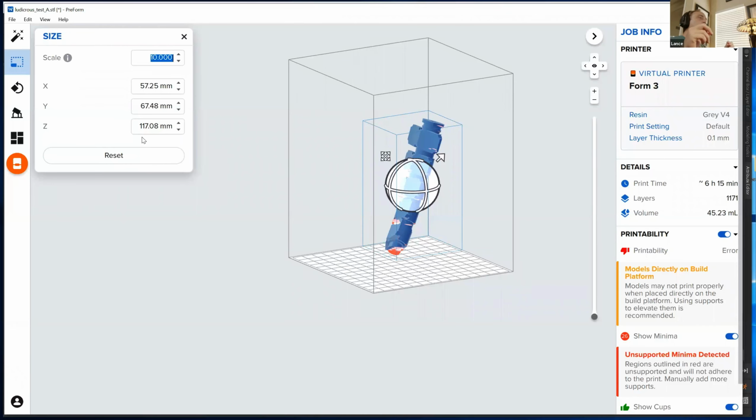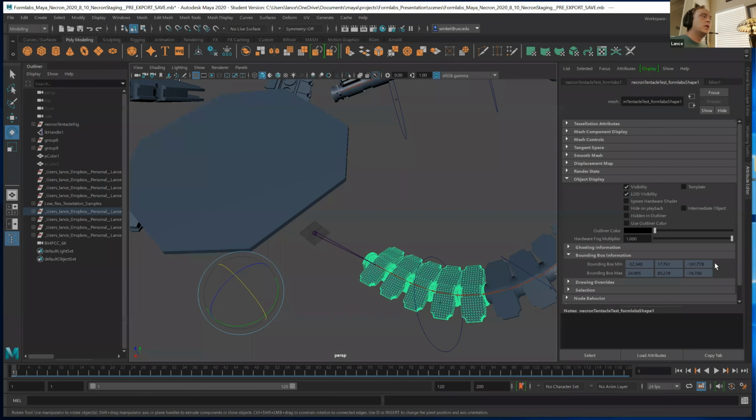Okay, so in Maya, if you're getting ready to export, this is where I create what we call a part index. And a part index is me going through with every 3D print that I'm going to send to a vendor. And I basically make like a little text file. Sometimes I'll do it in Excel or in another program where I can have it a little more automated. But with every model that I'm going to send to print with a vendor, or even for myself, just so I have a record of it, I create a part index that has the name of the object, the quantity I want to print, if it's got different materials, the material that I want to print from, and